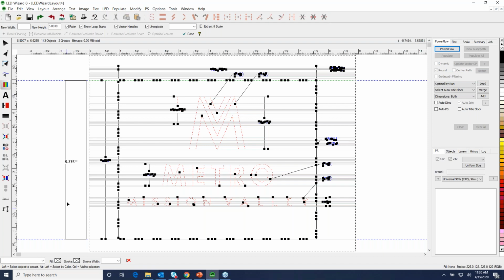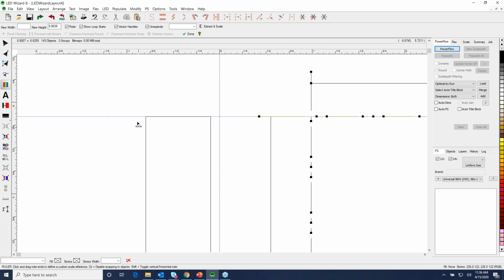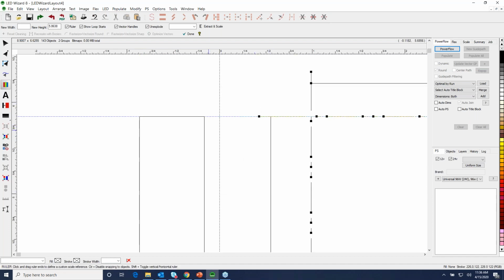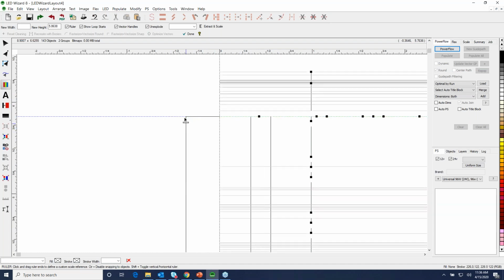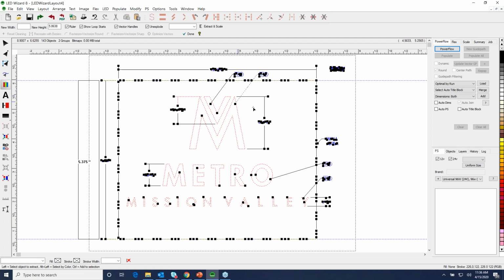So the ruler, you can see, got my guideline there, yeah. So the ruler, see how the cursor changes to the ruler? That means that I can grab that ruler, and the ruler is looking for something to snap to. And you can see all these different horizontal lines that come across that match up to various things in the artwork. But really, I created those guidelines. I can snap to those guidelines. Now when I zoom in here, I say, okay, I've got 10 feet.